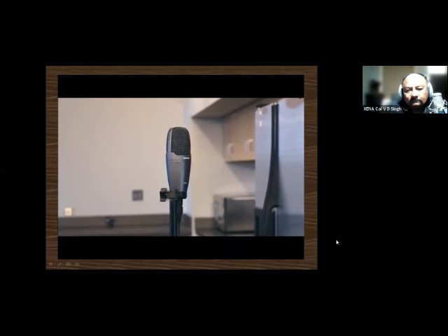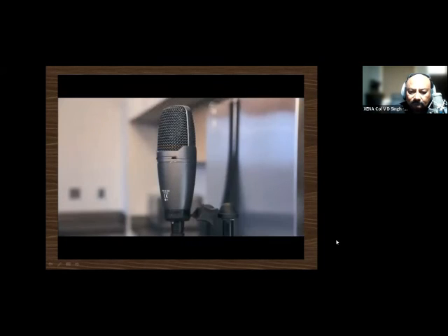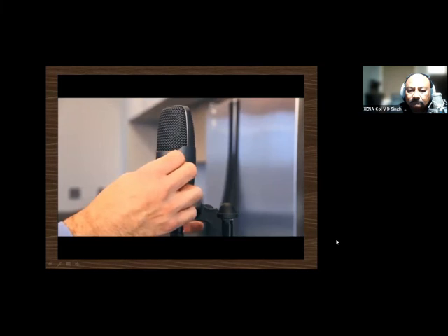I love you so. Some microphones allow the frequency response to be adjusted to match different sound sources or recording conditions. The most common is a low frequency roll-off control. In the flat position, the mic picks up low frequencies normally. In the roll-off position, the mic's sensitivity to low frequency sound is reduced.